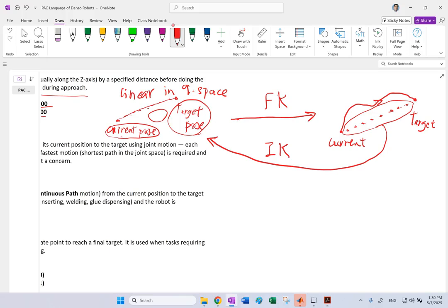So depending on whether you use the built-in forward kinematic functions or inverse, and of course, actually you don't really need forward kinematics for the P2P, because at the end of the day, what you command are the motors. The only thing you can command are the motors. So when you command them in the joint space by forcing the Q's to go to these desired values in between, this forward kinematics is done via the robot. You don't need to do a built-in forward kinematics. This is automatically done through the robot, and in the workspace you see the effect of it.